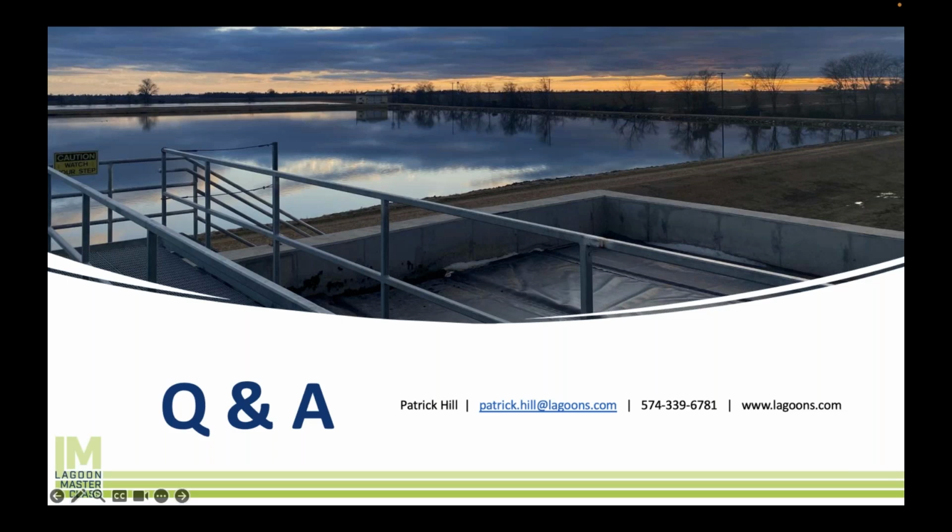Is there any level of denitrification you can get out of a lagoon doing nothing? Yes, absolutely. There is serendipitous denitrification across the lagoon system, and lots of mechanisms for it. Algae will assimilate nitrogen into their cell wall, and if they flow out, then certainly you have that.